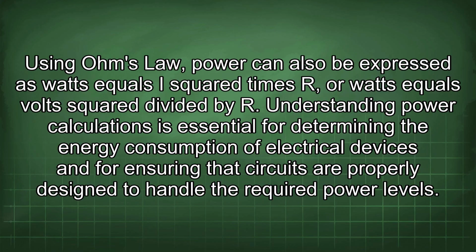Using Ohm's law, power can also be expressed as watts equals I squared times R, or watts equals volts squared divided by R. Understanding power calculations is essential for determining the energy consumption of electrical devices and for ensuring that circuits are properly designed to handle the required power levels.